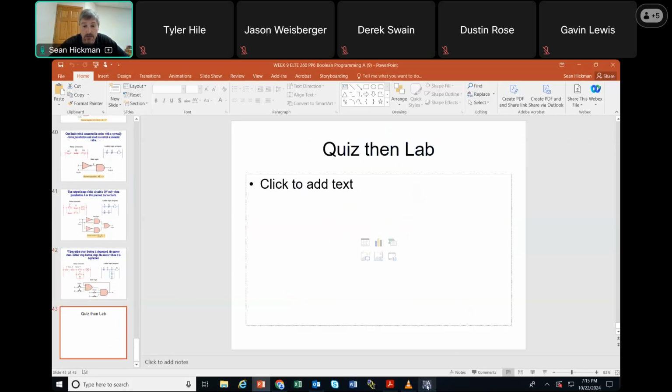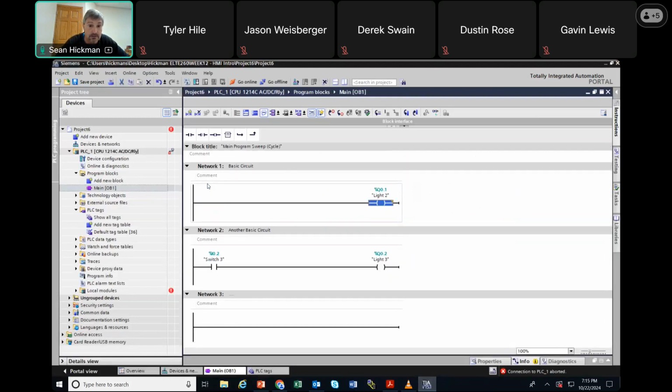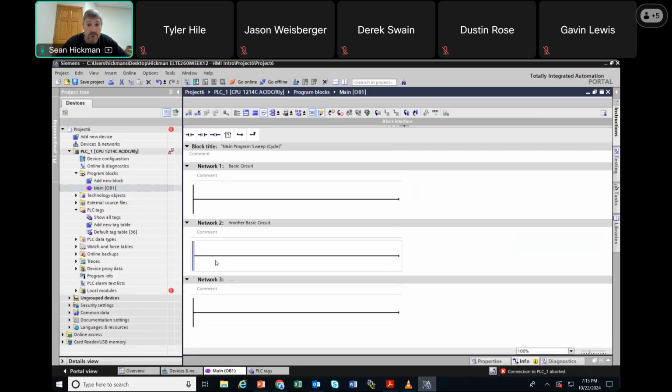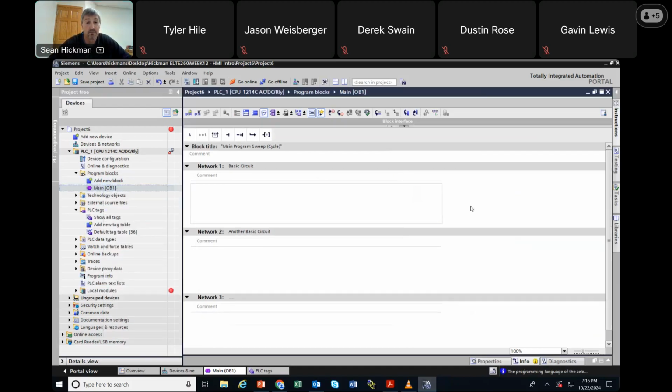I'm just going to show you one other thing real quick. I'm going to come right here. Can I just delete all this? Delete. Now just get down here and just delete. Okay. So now I've still got my program here where I created my tag table. And if I go into my main here, it says switch programming language. Here would be structured text, STL, but we don't have the right firmware in there. There's ladder, and here's function block programming, okay?